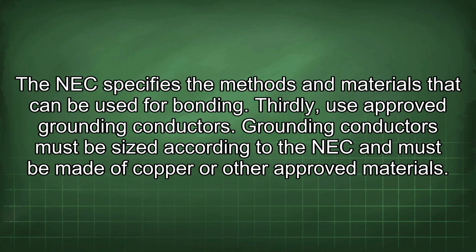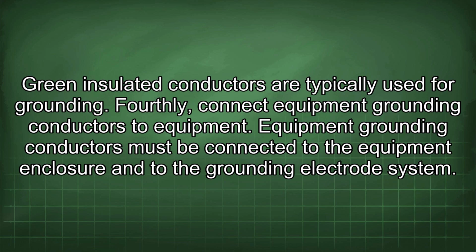Thirdly, use approved grounding conductors. Grounding conductors must be sized according to the NEC and must be made of copper or other approved materials. Green insulated conductors are typically used for grounding.